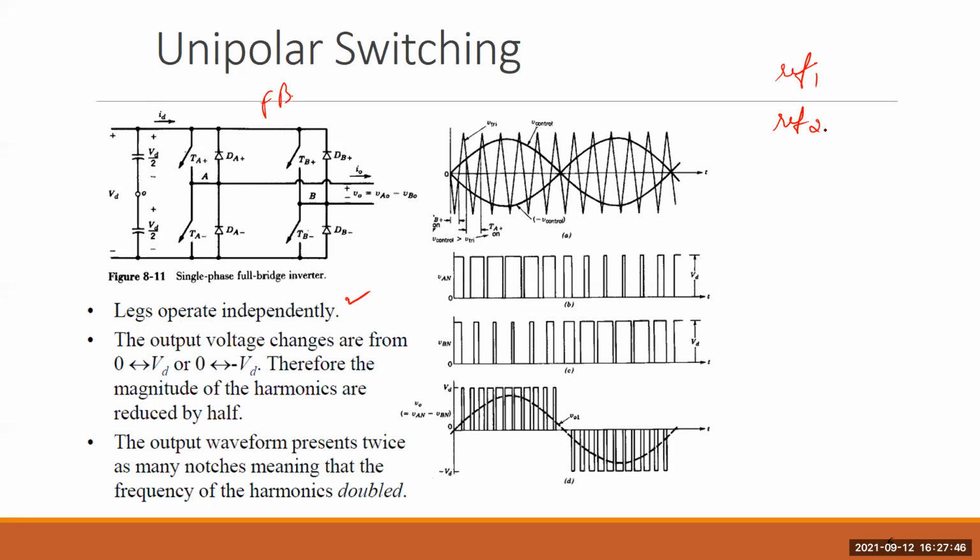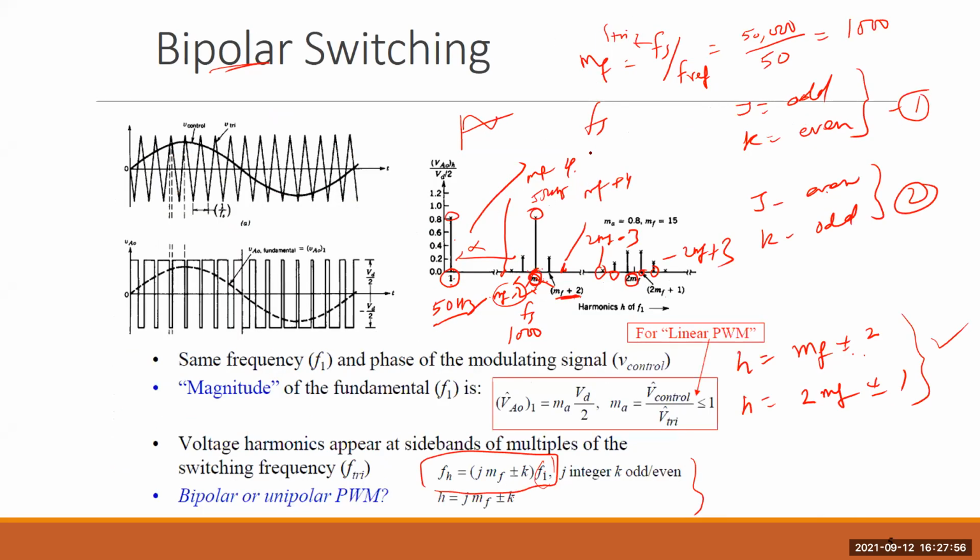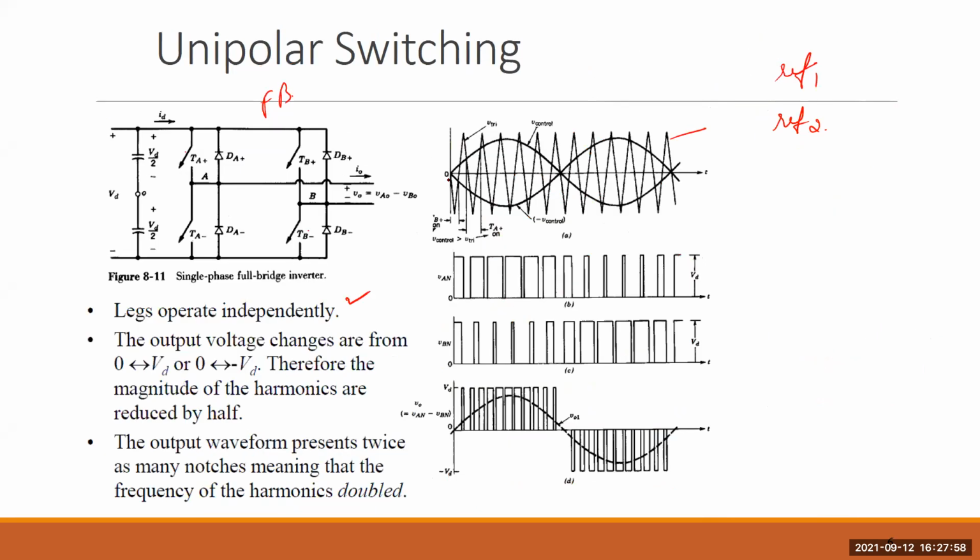So you can see the triangle waveform is the same as before. You can see it starting negative, positive, and so on, and this one is the positive reference, and now we have a 180 degree shifted, or opposite phase, reference. Okay, so now reference 1 and reference 2.